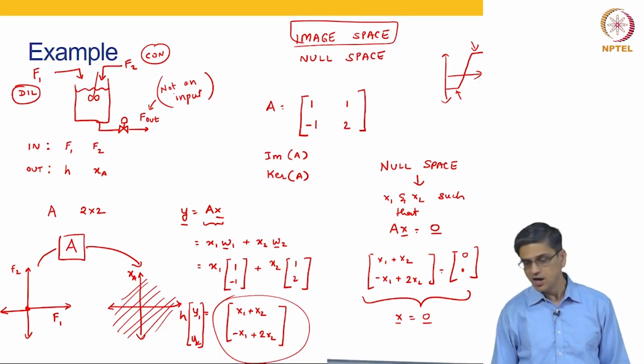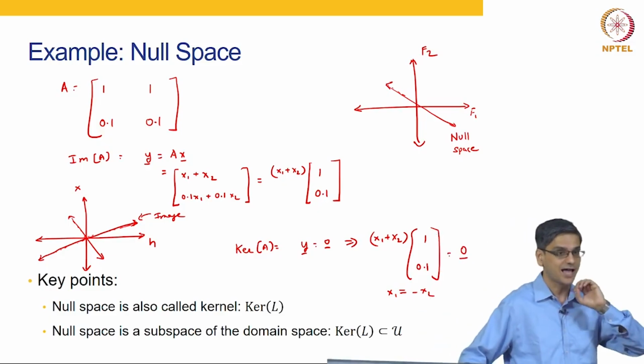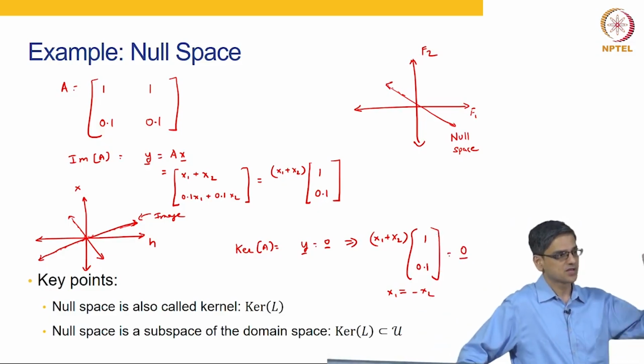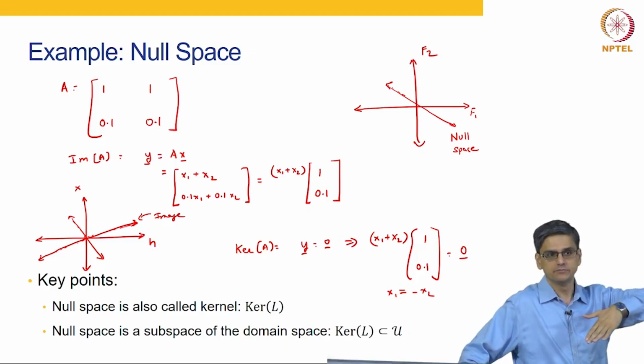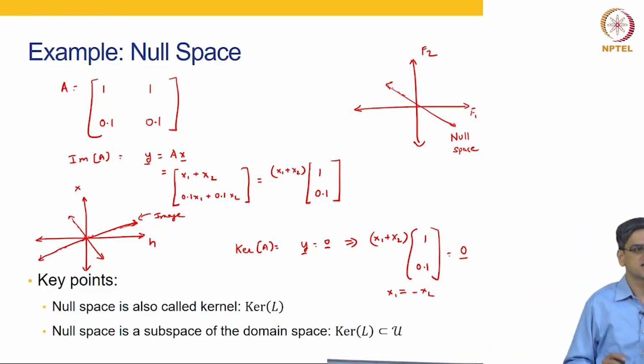And then the third case, I actually now thought of one more example in the third. This actually does happen. Let us say you are changing flow rates F1 and F2, and let us say F out was under perfect control, F out was always equal to F1 plus F2. So, therefore, we did not have to worry about height. Let us say an engineer decided that the two controlled variables are the purity XA and the purity XB. What is going to happen? XA increases by 0.1, XB will decrease by 0.1. Why? XA plus XB equal to 1. So, that could be another example.